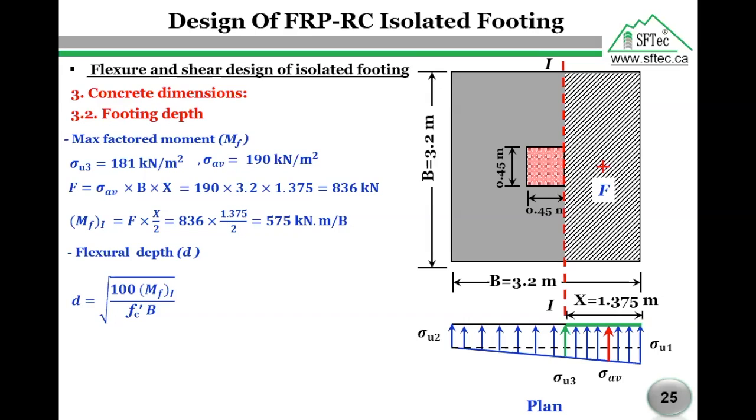This curve is related to the European codes, and this curve gives this equation, but without modifications, in order to estimate the depths. They mainly use this equation to estimate the depths of any structural element under flexure loads. So what I did, I modified this one based on the design cases I had in our company. I have a lot of design cases. I did a slight modification for this equation in order to get a reasonable value for the footing depths.